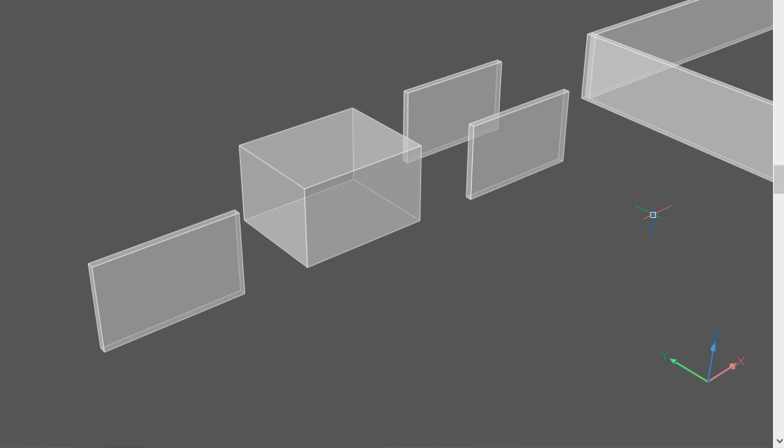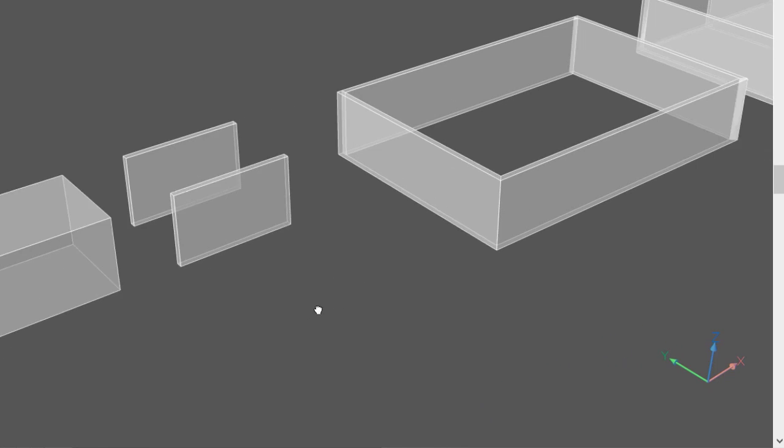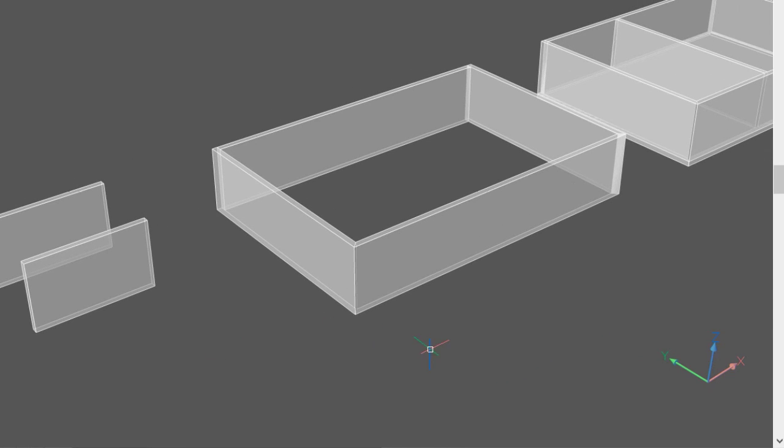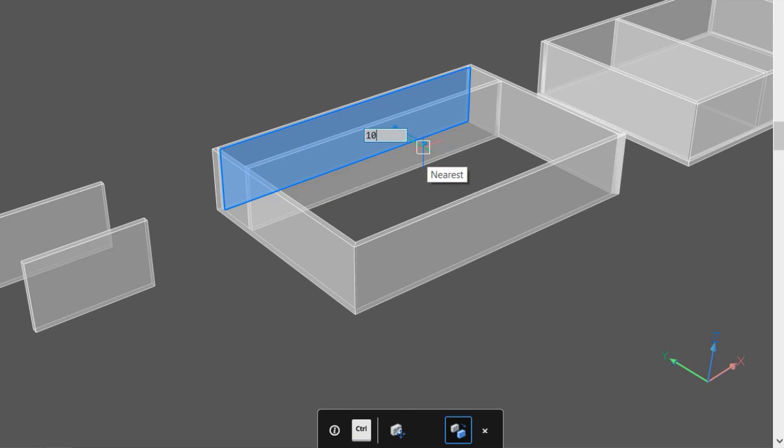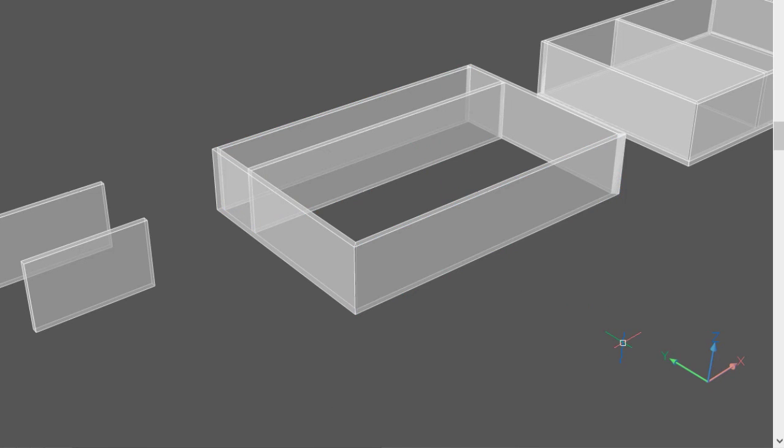The power of BIM Drag increases when other walls are present. In this scenario, we have 4 exterior walls. Highlighting the inner face of the wall and selecting BIM Drag, we are provided with the same 3 options, but in the context of the other walls. Remember, Tab can lead to other options as well.